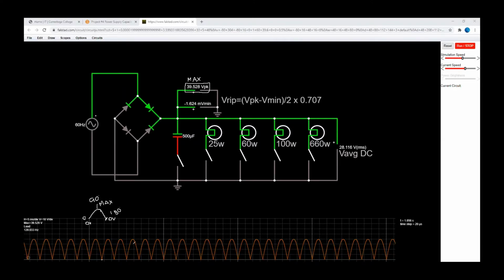Now, you may wonder, why am I giving you this at this point in time? That's pretty evident. It is because once we use this little guy here, which is called a capacitor, and we are going to be using a 500 microfarad capacitor, once we do that, then we can cancel that 0 volt. So we are going to be able to flatten the signal.